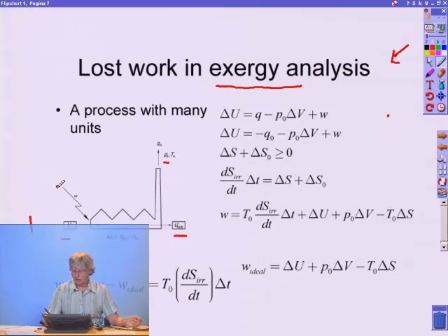Then we have again the second law in equilibrium thermodynamics. And the way we now write it for the whole system in non-equilibrium thermodynamics is to make the link to that field. And you can see that I can now replace delta S0 in this equation by Q0 over T0 of the environment, because the environment has a constant temperature. So that's the easy replacement I can do. And then I introduce the replacement for Q0 in the first law by this equation, and I get the expression for work that I'm interested in.